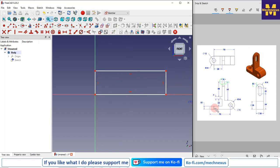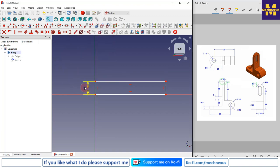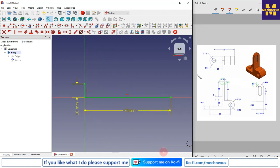and the height is 10. So I will select this line and give it a height of 10, and I will delete this line for the time being, and I will also delete this line. Then I will give this dimension 70. Then I will draw a 3-point arc of radius 14. From here I will select the 3-point arc,